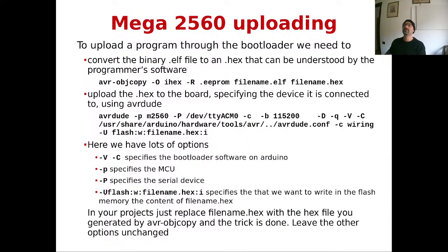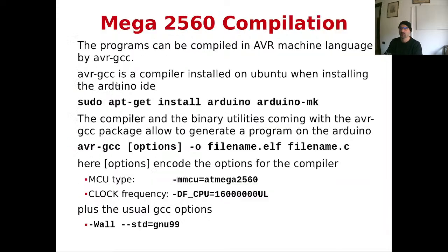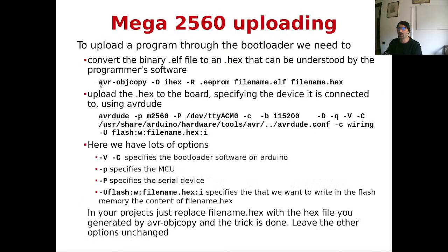Yeah. This is typically done by another file, which is AVR object copy. What it's typically doing is you just ignore it and you always use this line, AVR object copy, where the output is a file name that ends with the hex destination, which is ready to be fed to the microcontroller, to the bootloader, and the input is an ELF file.